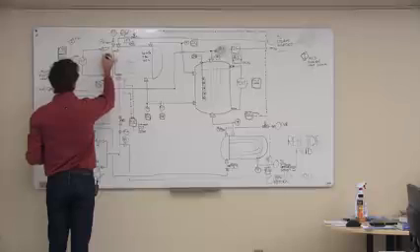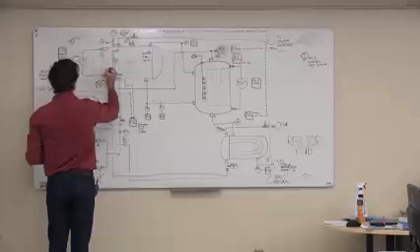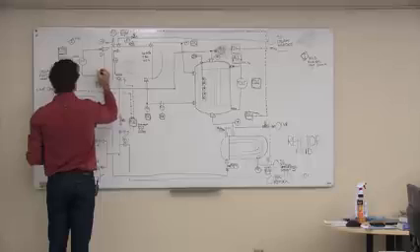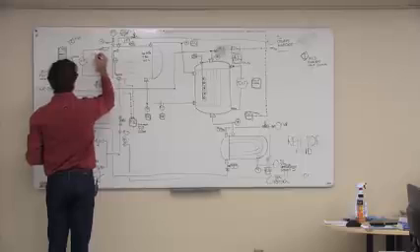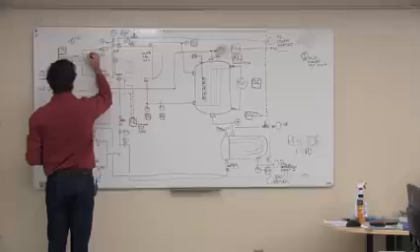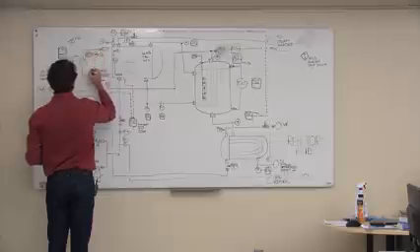You might be smart to put a couple more nozzles on here with level switches. Like that. And a level switch high. Like that. Level alarm high. Like that in the DCS. Low.